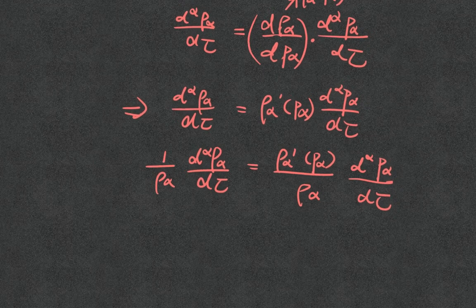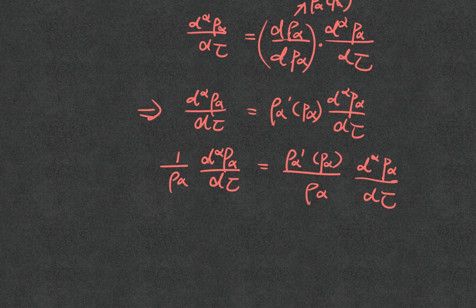Okay, so what is convenient for the UP formulations? I need to write everything in terms of P, and I want to write everything in terms of solid displacement, right? So what can give me the displacement, or some kind of displacement functions? If you take a derivative, you get the strain, right? Now, if you look at this expression, there's no way I can put the strain here, right? Okay, so P is good. I want to keep the change of the P term.